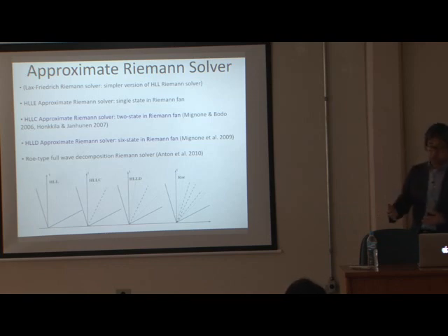I think a smooth structure may be okay, but if shock wave structures happen, then the sharpness is usually broken up by numerical instability. So at least in my understanding, the sharpness and the diffusivity are mixed up. The diffusivity keeps the calculation more stable because the method is not perfect yet.